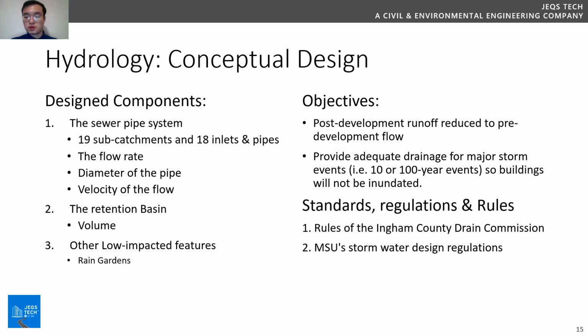The company decided to add some rain gardens in the parking lot area to reduce the runoff coefficient, so that some of the rainfall will be stored rather than flow into the system. Due to the pavement and the transportation design from another specialist, the whole area was surrounded by grass except the roads and constructions. The grass is another feature that was added into the design. The soil is under the grass area, thus the stormwater will infiltrate into the soil.